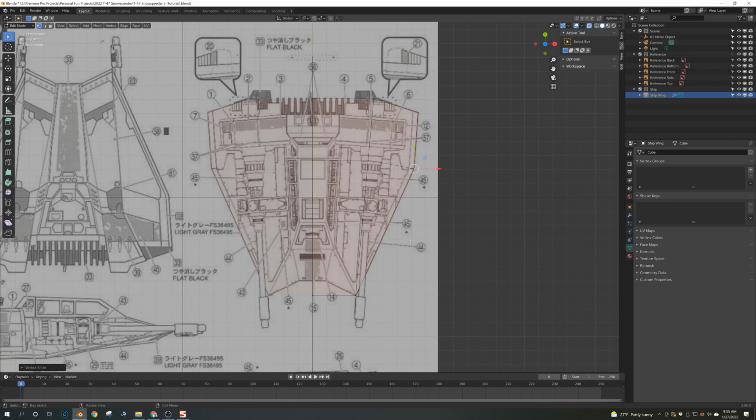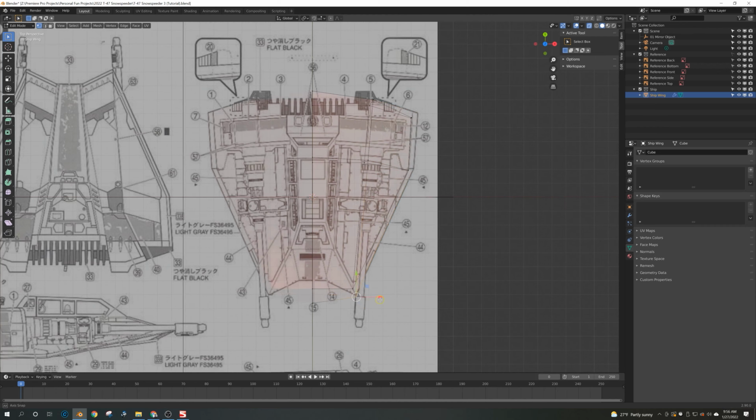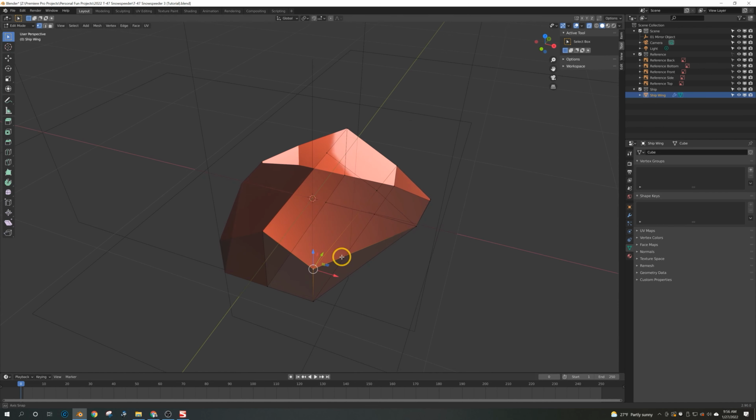So what's going on in my mind as I'm doing some of these edits on these vertices is I'm just trying to take what I think is the best step in the moment. Just because I've brought some vertices together, I'm going to select all, M, and merge by distance. And down here in the info panel, I see that I did in fact clean up the mesh, and now I've got no overlapping vertices.